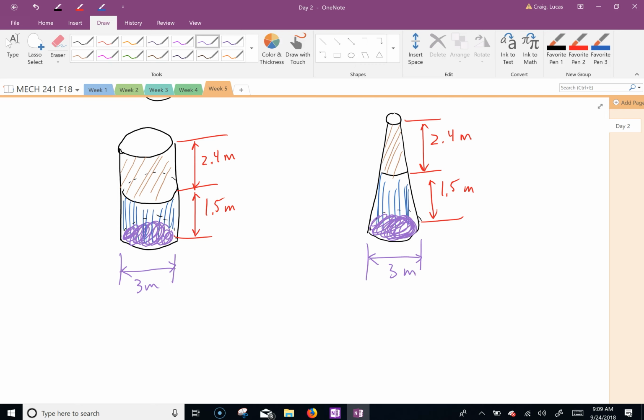Well, say they're both open to the atmosphere at the top, then you would get the exact same amount of force at the bottom. Okay? Because we know pressure is a function of depth only. So if we want to figure out what this pressure is, well, say they're both open to the atmosphere up top. So sometimes you'll see this triangle. So it's P atmosphere plus rho of the oil times g times h. And we'll call these h1 and these h2. Plus rho of H2O times g times h2.